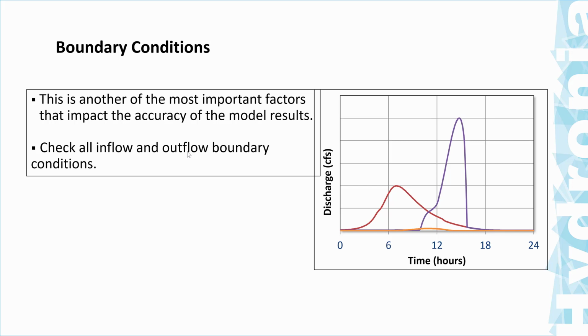So if you use the model as a hydraulic model, you need an inflow hydrograph similar to the one you see here, where you have a variation of discharge with respect to time. And that will be the discharge that will enter by the inflow condition to the mesh.